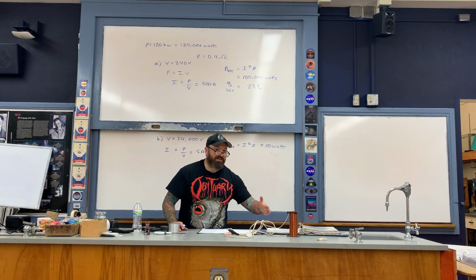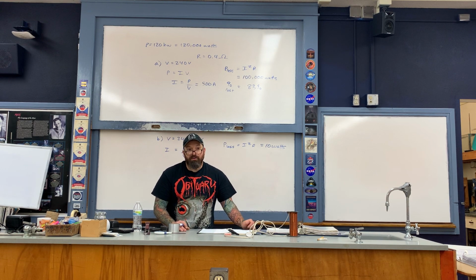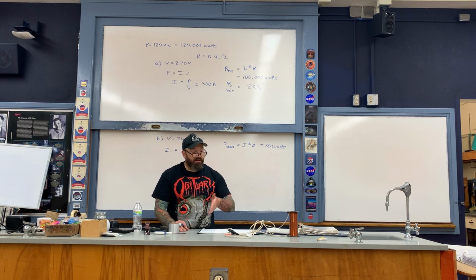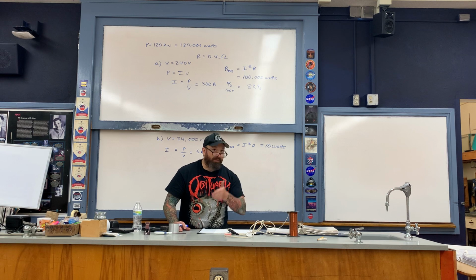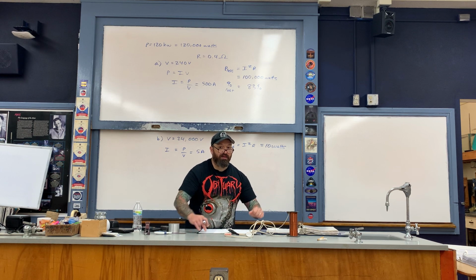They usually do these in stages, as what are referred to as transformer substations. There is, for example, a transformer substation that you may have driven past on Lincoln Boulevard. There's actually a couple of them. There's one on Lincoln Boulevard in Santa Monica, and there's another one at the corner of Lincoln Boulevard and Fiji in Marina del Rey. Those are step-down transformer stations. So what they do is they repeatedly step down the voltages by using these transformer substations, and then they eventually send that out to the city.